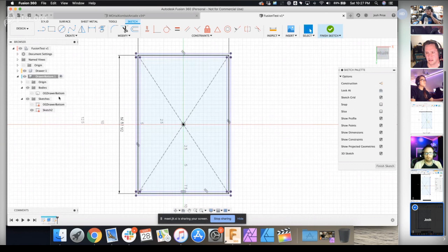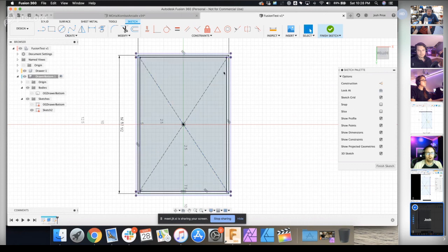So let's try one more thing. Let's hide that. Never mind. No, I don't want to confuse you. You can also do what's called offset. Does everybody have offset in their modify menu up here, right next to these scissors? Yep. So if you were to highlight the walls on the inside and create an offset, you could offset outward the dado thickness as well, and that probably would have given you the same thing. An offset is a derivative measurement. So if you were to derive an offset off of this wall, which is updatable, then your offset will update as well. That makes sense?